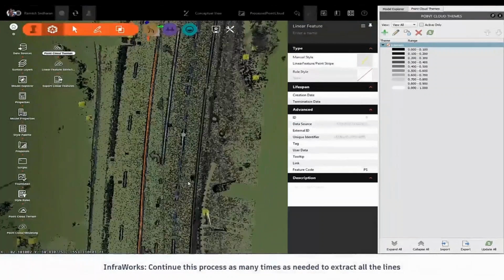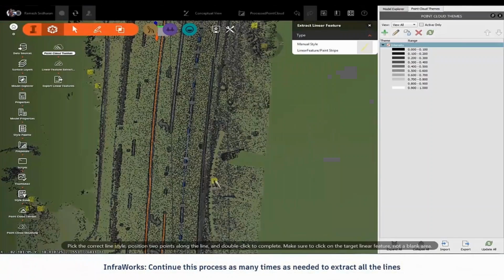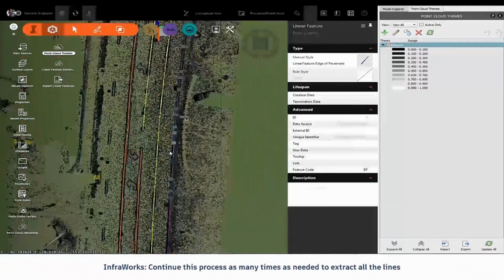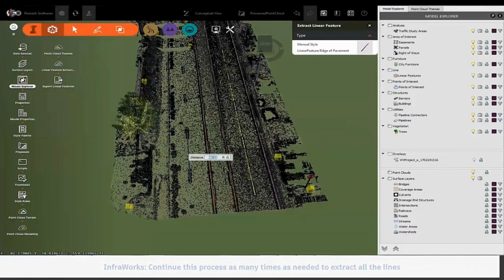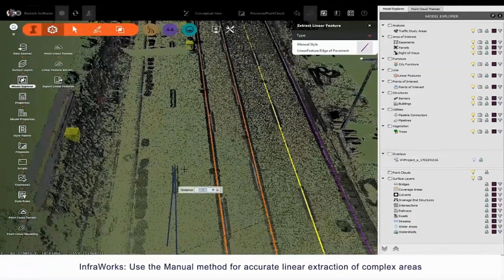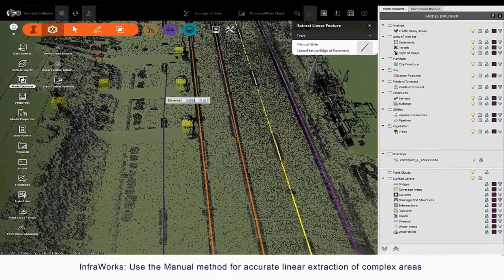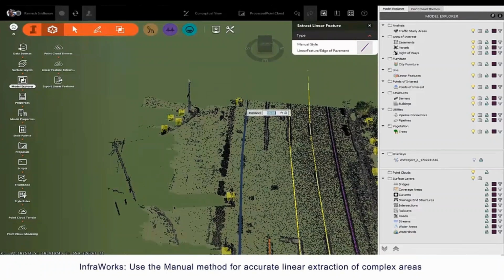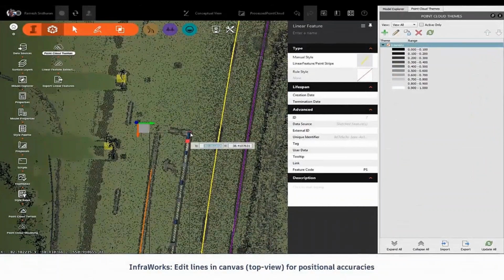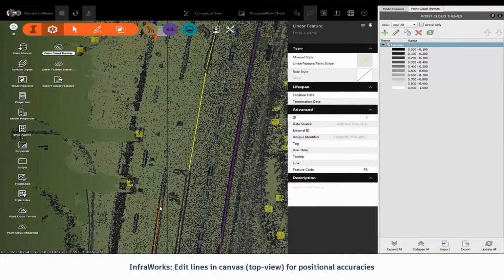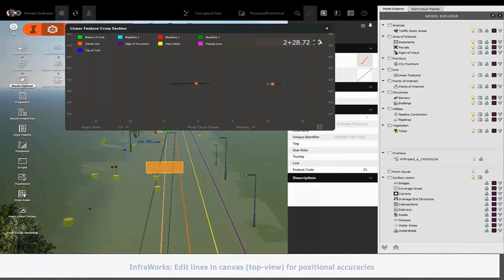So basically depending on whether at this point there is really a feature line, because sometimes this can disappear from the measurement, etc. But we do have tools which do it automatically, and then if it fails for some reason, because as I mentioned, maybe there is a change of super elevation and this center line is kind of disappearing, maybe you have to do it manually.